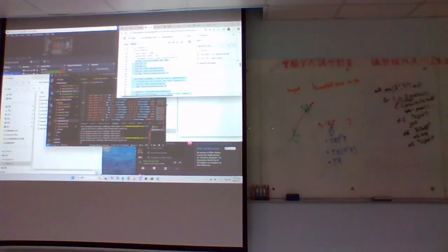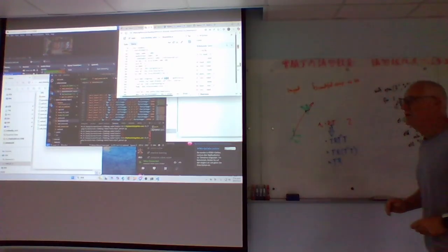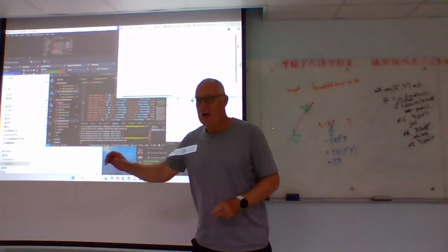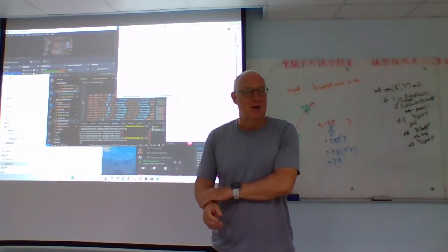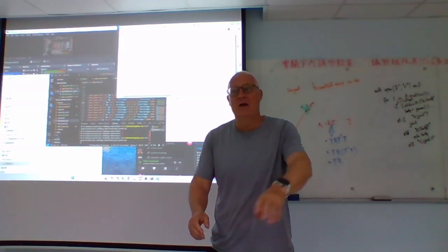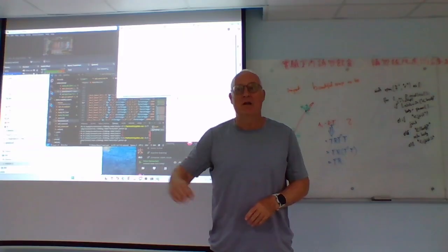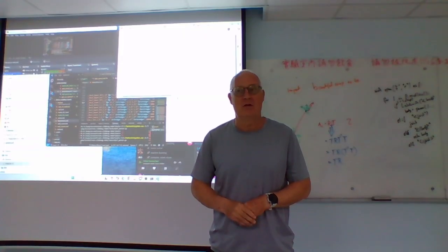So we look at the current position and my target, and I calculate the current position in forward kinematics, and then my error. So it's an approximation step. What you basically do is check how the value changes when you change joint 1, joint 2, joint 3, joint 4. Then you move joints 1, 2, 3, 4 and 5 all in one step, a little bit in the direction that you think moves it closer to the target.